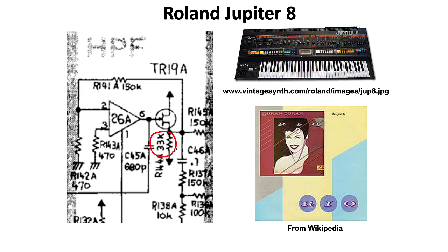So the 33K here isn't that big of a deal. You have the JFET through this resistor to the negative rail. Here we have the drain of the JFET hooked to the positive rail voltage. And all this does is provide a nice high impedance buffer to buffer the output of the OTA. And then the current control circuitry is generated elsewhere. So here we have a one-pole high-pass filter.